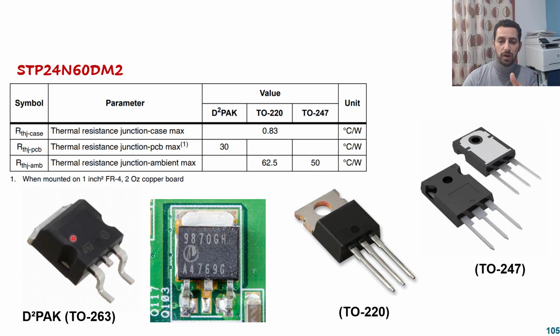So that's why it's like an SMD component, soldered on the surface of that PCB. And it says here that junction to the PCB through the case will be 30. And you have to maybe calculate also the thermal resistance of that PCB by some other ways to get the final temperature flow. But we will not consider this now.